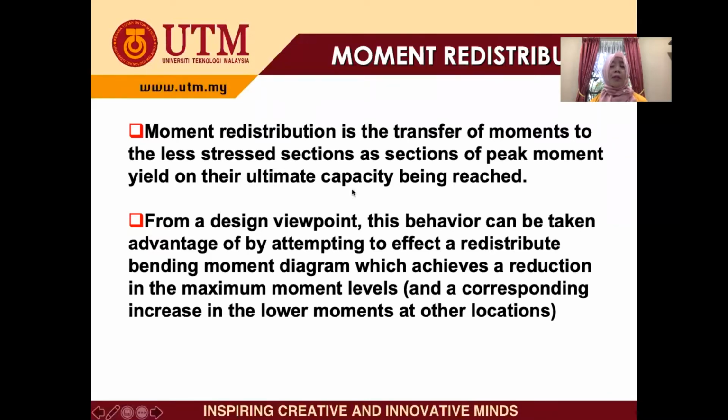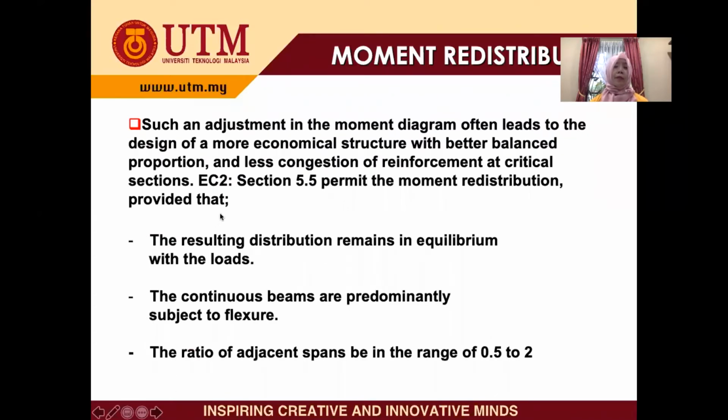Okay, another thing is that here you will come across moment redistribution. Moment redistribution is the transfer of moment to the less stressed section. This is actually an advantage, because it reduces the usage of steel at the support. We can see later.